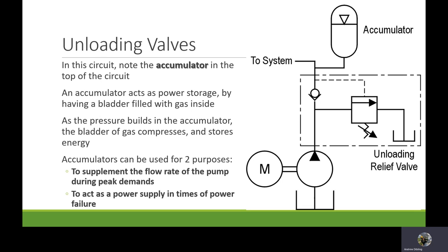So upon a loss of power in a wind turbine, the blades will turn 90 degrees and turn themselves out of the wind. This is done by accumulators because those blades are positioned by big hydraulic cylinders.